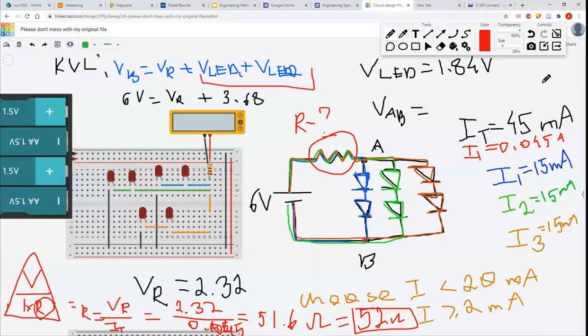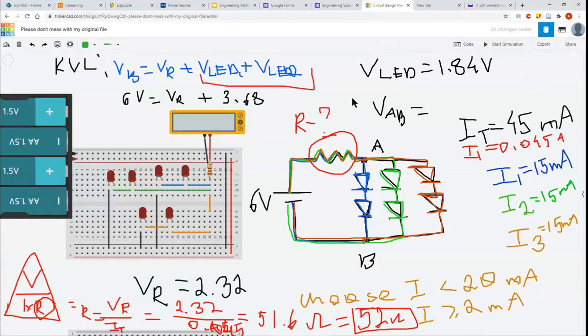So let's go ahead and test this thing out, okay? What I'm going to do now is change the value of my resistor to 56, and we're going to run the simulation. As you can see, nothing burns out. Our voltage drop went down a little, but that's okay. I always say that no calculations meet reality and survive intact. Because the numbers we get are fairly close to the numbers that we had, we're good to go, really.